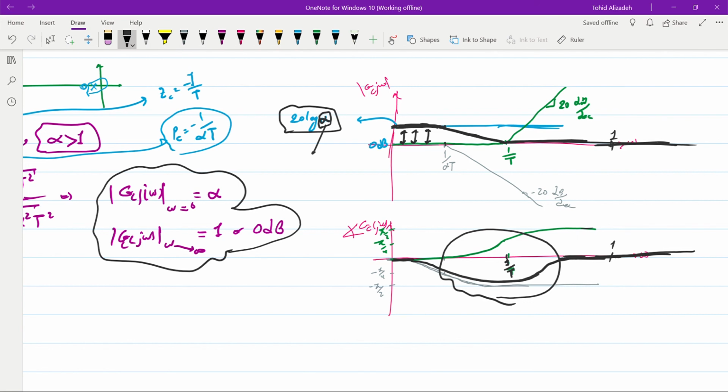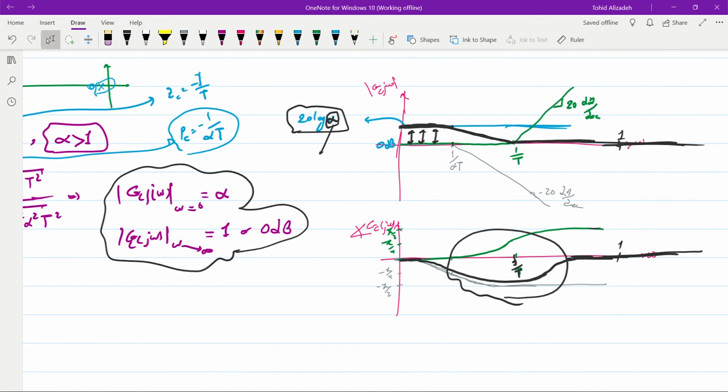It's indeed similar to the flexibility that we had in designing the controller using the root locus, because over there we were able to pick the location for the 0 and then find the location for the pole. And here we have somehow a similar case. So we will find the exact value for alpha that we want to have, and then we will pick a value for 1 over t for the location of the 0 based on the Bode plot of the whole system without the compensator, such that we don't touch the Bode plot of the system around the crossover frequency by introducing this compensator.